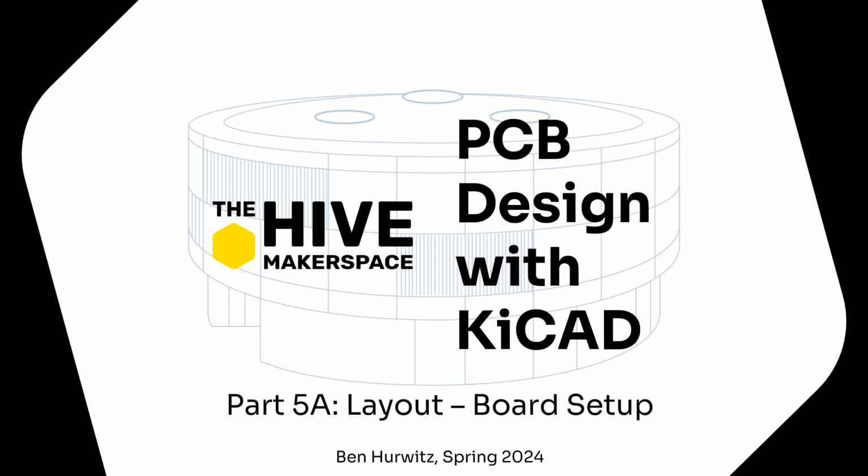In these next few videos, part 5A, B, and C, we're going to shift focus to the layout portion of the design process, which KiCAD calls the PCB view, which will actually be physically aligning and orienting the components on the board and connecting them with traces. In this specific section, part 5A, I'll introduce the board editor and look at setting up some of the board's defaults and design rules. So let's get started.